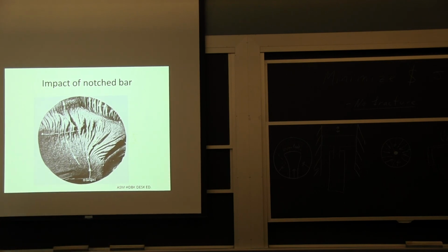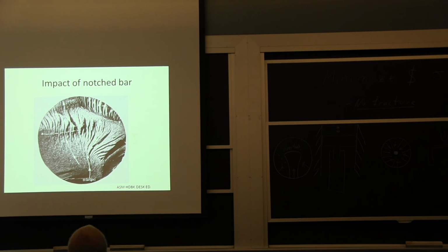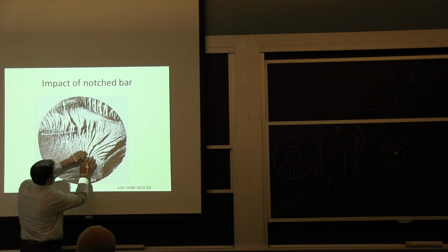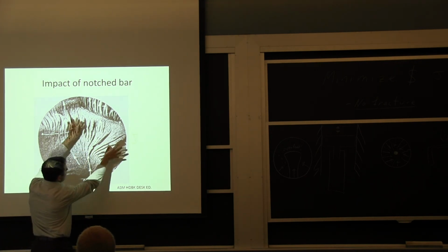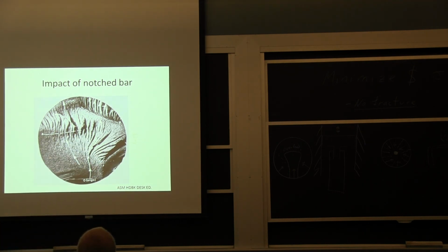And because we're looking at a macroscopic level here, it's fairly straightforward to say that from the initiation area, the crack propagation lines will diverge. There are other lines on the fracture surface that will converge, but we'll treat that separately.